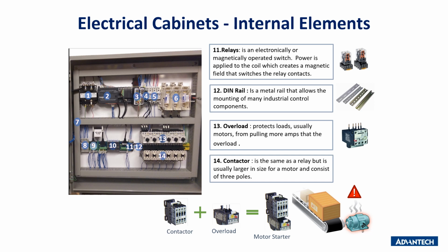13. Overload protects loads, usually motors, from pulling more current than expected. 14. Contactor is the same as a relay but is usually larger in size and used for a 3-phase motor. An application of this is a motor starter, which helps to switch the power automatically or manually to a motor and at the same time protect the motor from overload or faults.